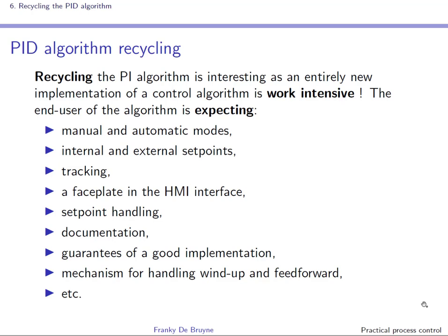In the next section, we will recycle the PID algorithm for a number of control applications. The control algorithm is modified, but instead of implementing this modified algorithm in an FB, in a function block, we recycle the standard PID algorithm that you can find in the control libraries of the vendors. And we do this because it is ready for use and comes with a nice faceplate.